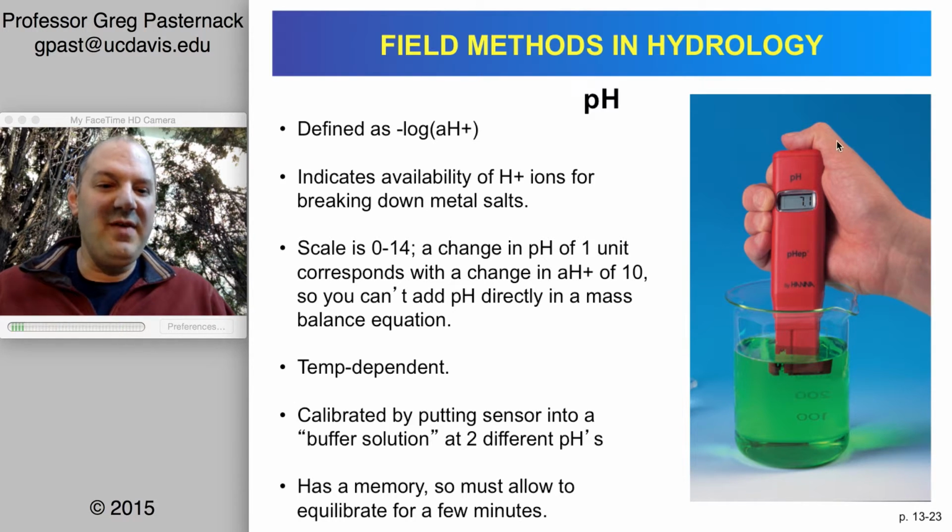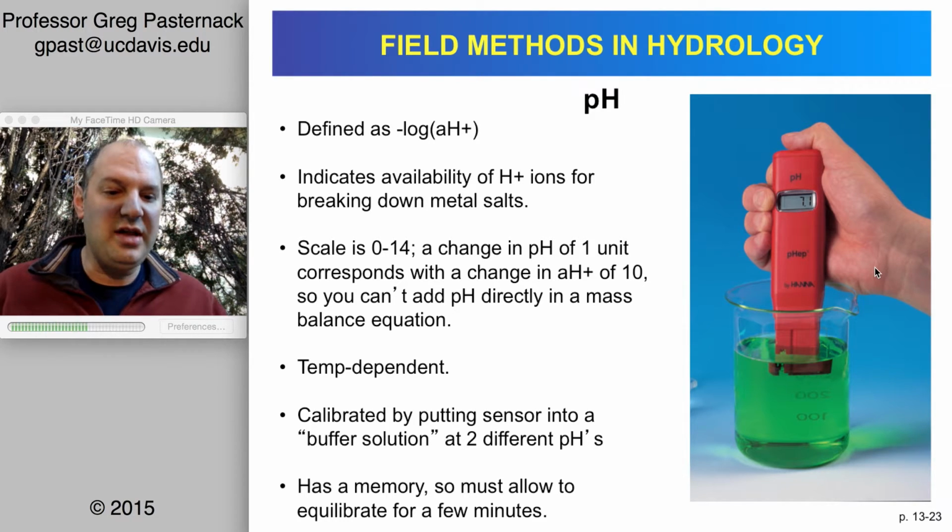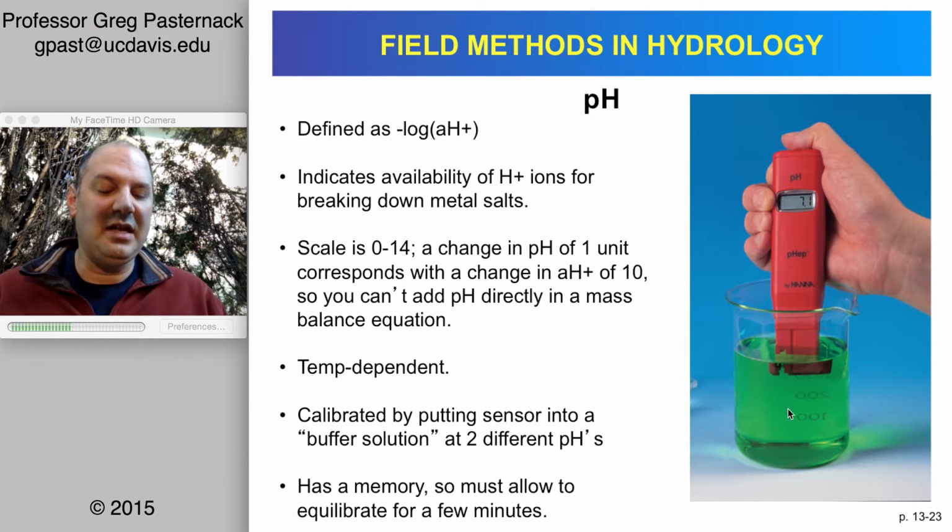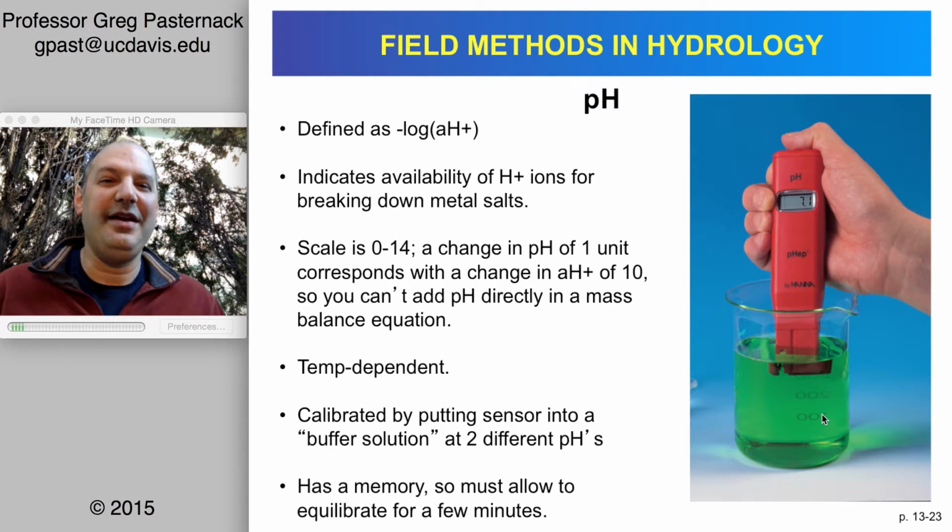So there are very inexpensive pH sensors that are out there, and there are also very expensive ones. The main difference is really, again, in the electronics and in the quality of the membrane that allows the hydrogen ions to pass through it. Also, consider that with pH, if you have a pH 2 or 3 fluid, you have huge numbers of ions, where if you have a pH of 10, you have like a tiny fraction, right? 1 times 10 to the minus 10 as your activity. So, having different solutions is something you have to be very careful about with using the same sensor.